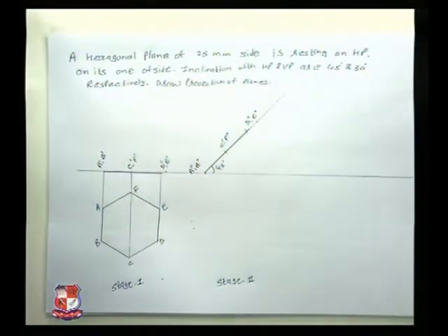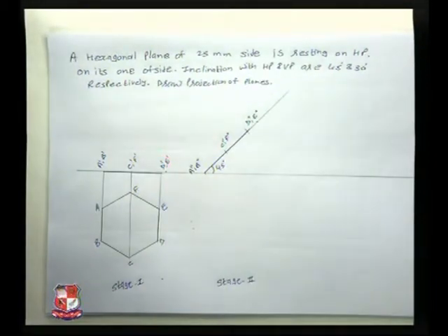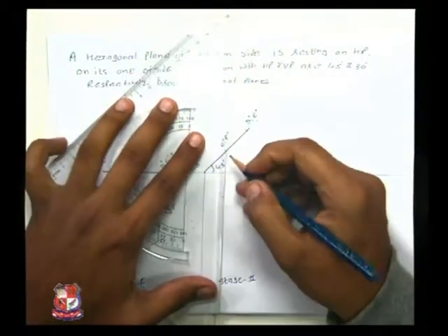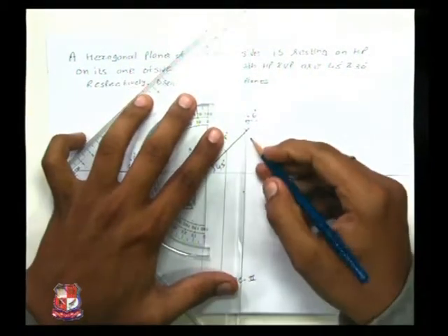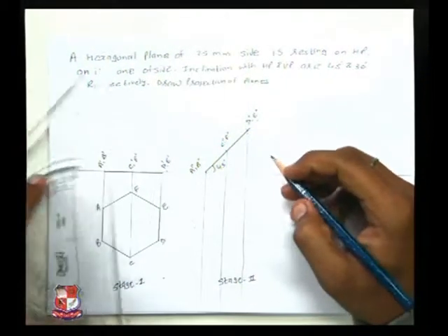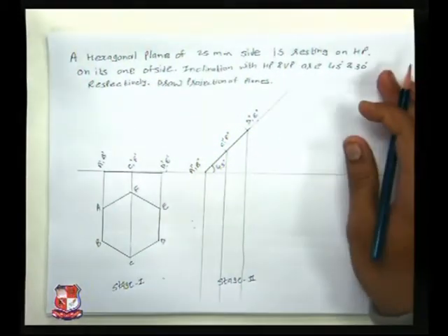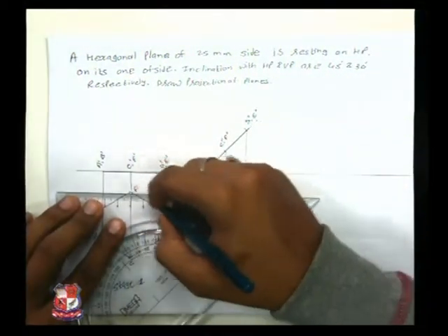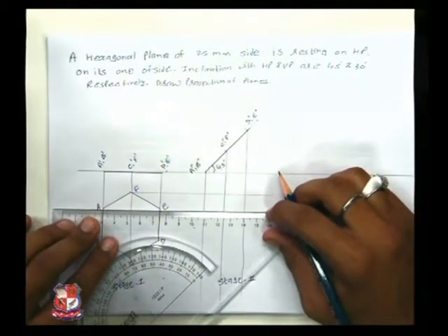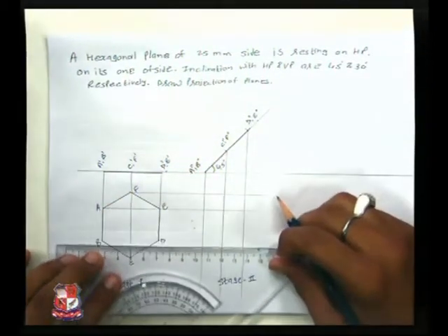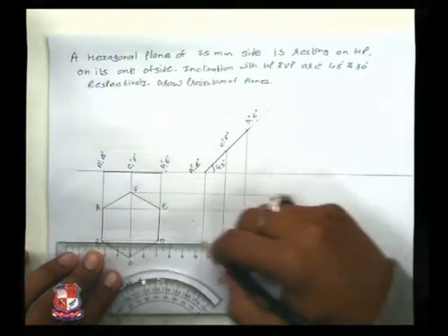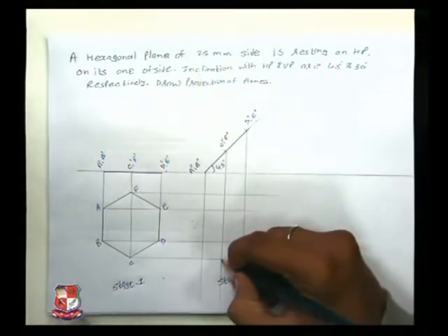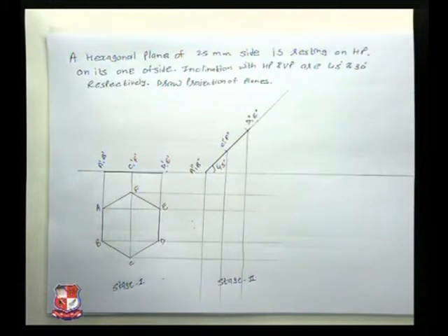Now we need to take vertical projections of it towards the downside. We have taken the vertical projections, which will match with the horizontal ones. Join the respective points.